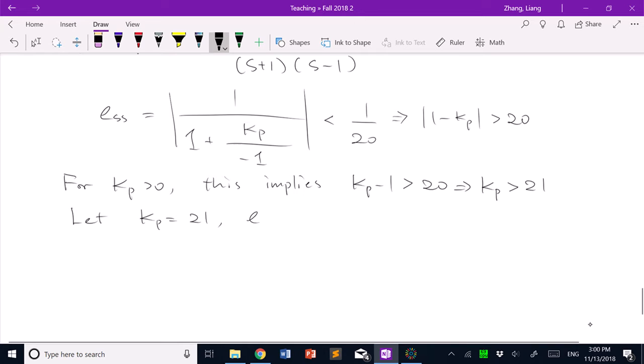I'll just treat the boundary values such that the steady state tracking error, when you plug that in, is negative 0.05. Okay. What it means is the steady state output is 0.95, so it's 0.05 less than the reference one, since E is defined as R minus Y. Okay, I'm sorry, let me backtrack this.